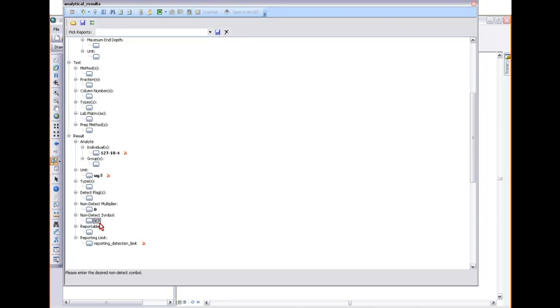So you can use that for labeling. You can have it do the label, just have it say ND, or you could have that label actually say less than the detection limit. But for this facility, most of the detection limits are the same. So 1, I think they are. So I'm just going to go ahead and put ND. Again, you can change any of these defaults in your database. If you want it to default to ND and 0, we can do that.